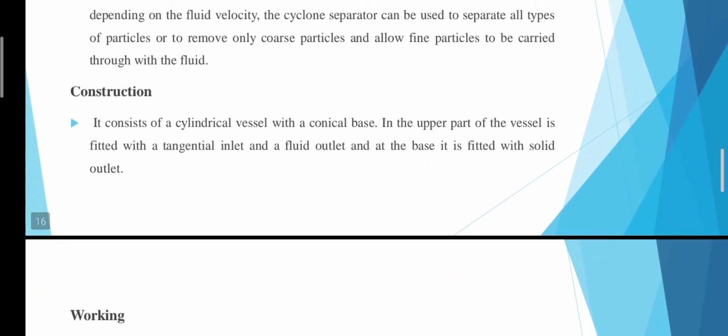With the help of centrifugal force, coarse powder goes down, and the air and fine particles move with the fluid. On the basis of centrifugal force, we separate out coarse powder and fine powder. Construction: how is it constructed? It consists of a cylindrical vessel with a conical base.